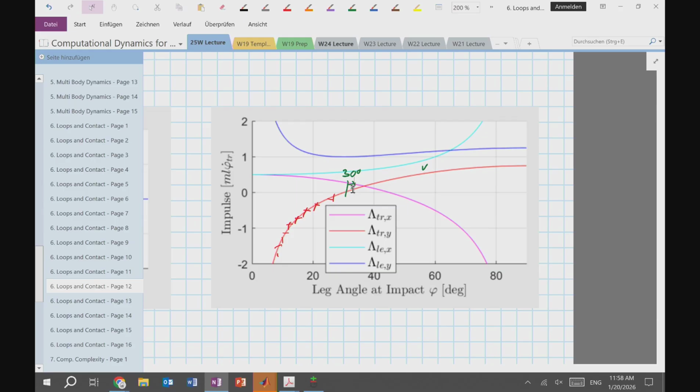This would be our F friction, and this would be the force with which I have to pull, which has to be equal to the friction force. And we're done. So an infinite coefficient of friction does not necessarily mean friction forces go to infinity. It's just about the direction.